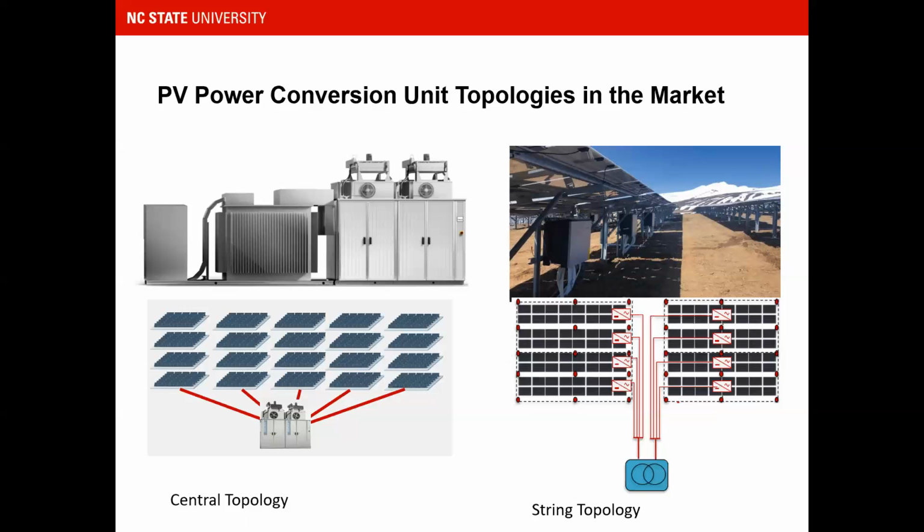However, we also have a disadvantage. The main disadvantage of the string topology is overall higher installation costs, due also to the additional electrical equipment that must be added to the solution, like DC disconnector, panel boards, AC disconnector, etc.